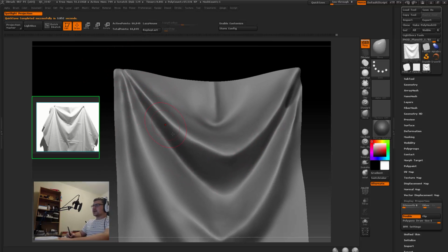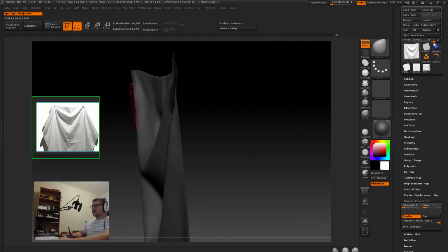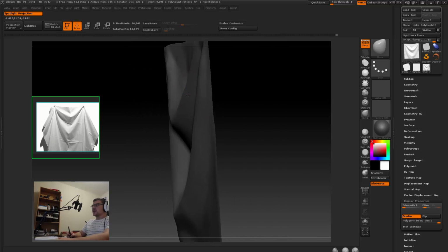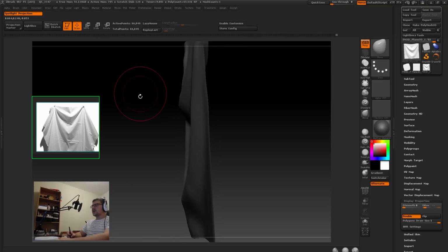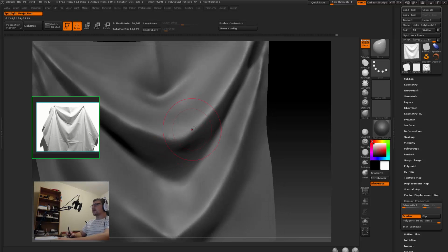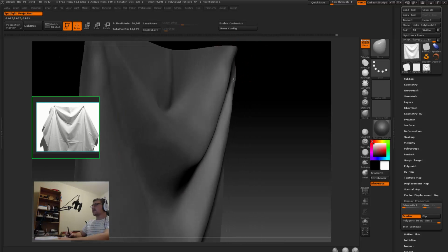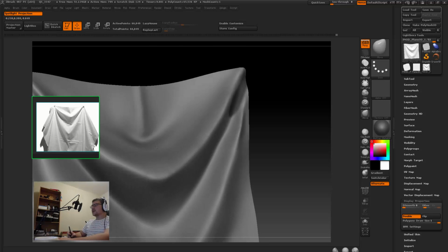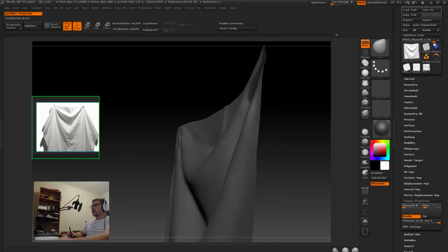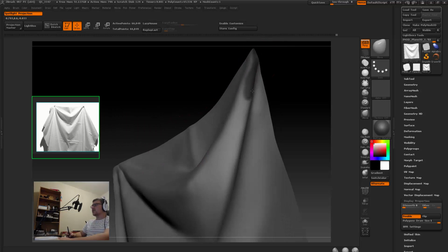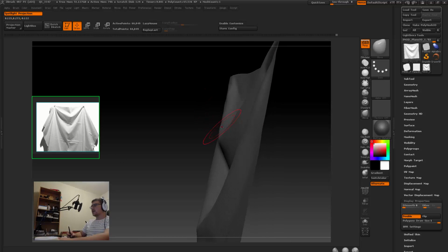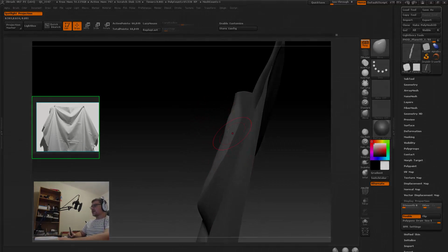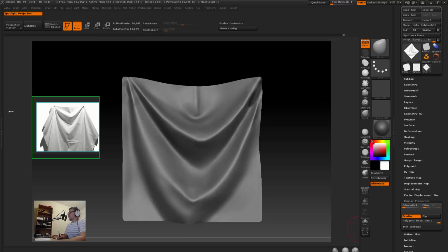And the most important aspects that you need to consider is the height from how far it's pushing forward and then collapsing backwards. So you want to create enough silhouette change in your mesh. And then also you need to make sure that these lines are as clean as you can possibly make them, with a weighted bowing down on the outside and more of a concave volume on the inside. And then making sure your high points are all one continuous line stroke throughout that mesh. You can see over here it's still a bit lumpy, so I'd spend some time trying to address that.